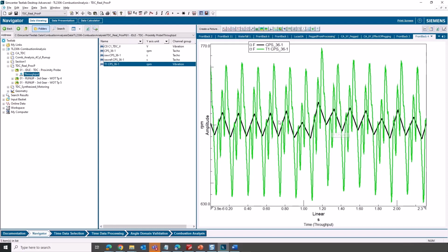And we can see that when you have the multi-pulses per rev, you can see a lot more dynamic content in the signal. It captures the variation in the RPM in a more detailed way compared to the 1 pulse per rev. That type of detail is important when you are transforming the data from time domain to angle domain, and that is why we should try to get as many pulses per rev as possible.